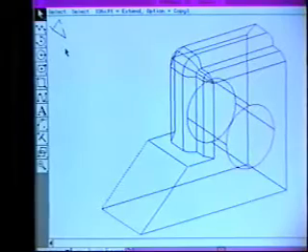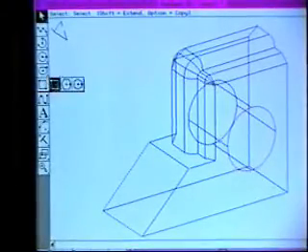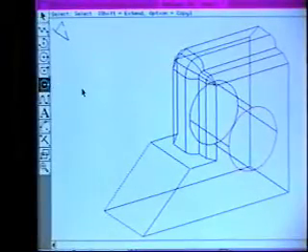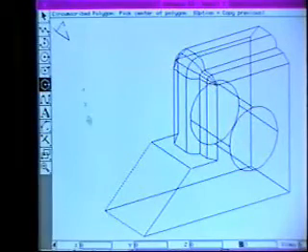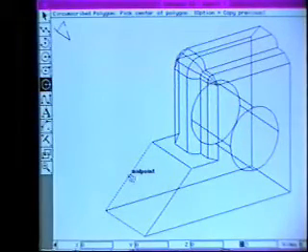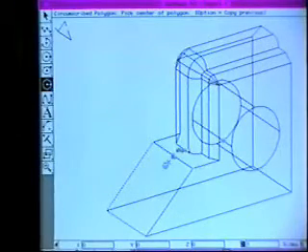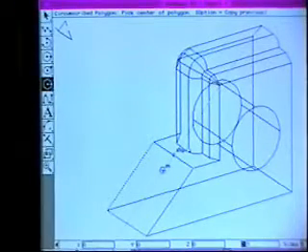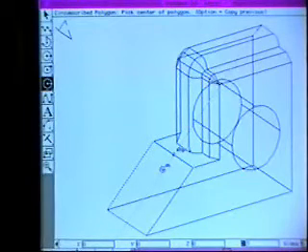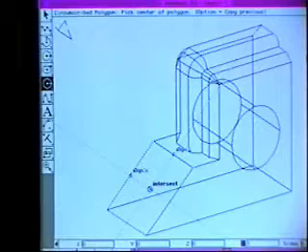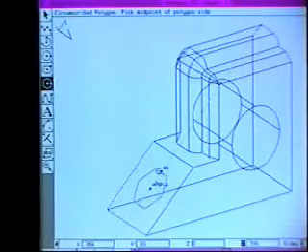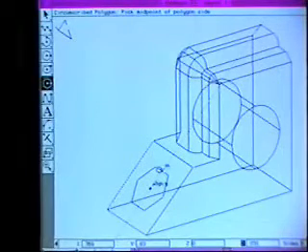So now I'm working right on that face, so I can go and I can pick one of my polygon tools, and this will work with a hexagon, and that's fine. Here I can touch a midpoint and I get a line X, touch a midpoint and I get a line Y, which you can't read there, but that's what that says because the work plane is flat to X and Y there. Go to the intersect and pull a hexagon right on that face.